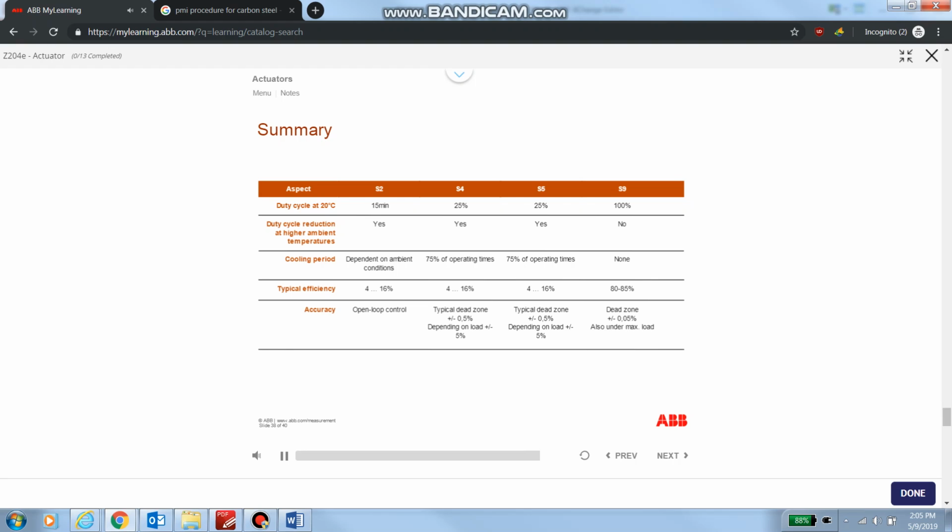The fields of application for this operating mode are the usual ones. Shut-off valves, for example, are valves which are normally either fully open or fully closed and which are very rarely activated, sometimes only for start-up and closing down operations. Simple control loops are control applications for low demands, for example, slow temperature control circuits. Control applications with high and very high demands are, for example, pressure reduction stations, spray water control valves, fan speed control, etc.